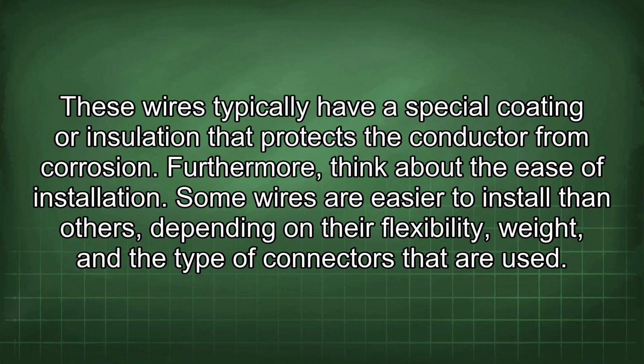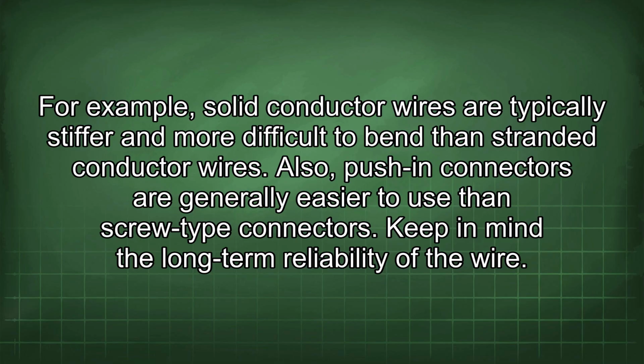Furthermore, think about the ease of installation. Some wires are easier to install than others depending on their flexibility, weight, and the type of connectors that are used. For example, solid conductor wires are typically stiffer and more difficult to bend than stranded conductor wires. Also, push-in connectors are generally easier to use than screw-type connectors.